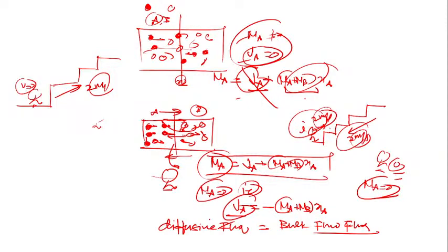And in design of equipment, which flux is important? Na. Why? Because in design of equipment, the total molar flux is more important. As far as a fisherman is concerned, he is more interested in the rate at which the fish is coming to the hook. A fisherman is never interested in the individual species, the velocity of fish with respect to the stream velocity.